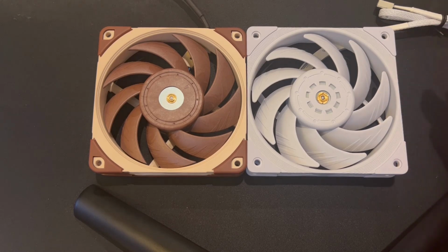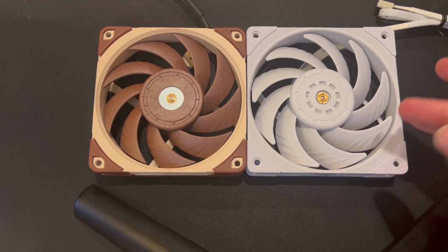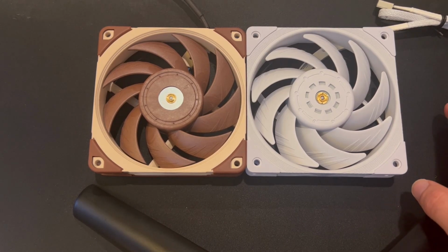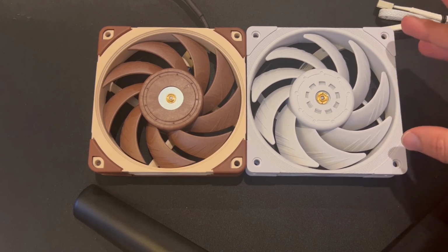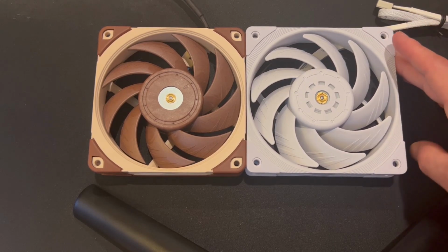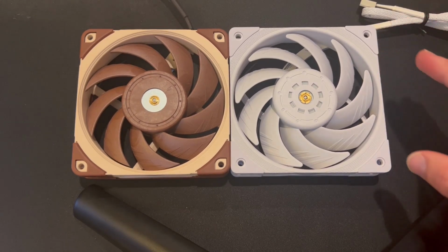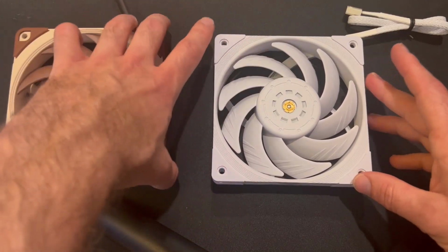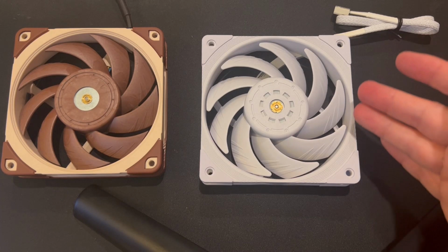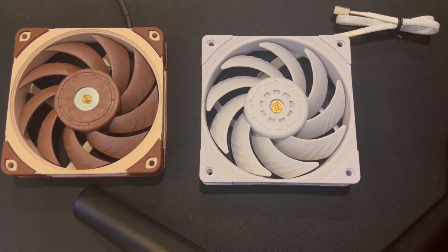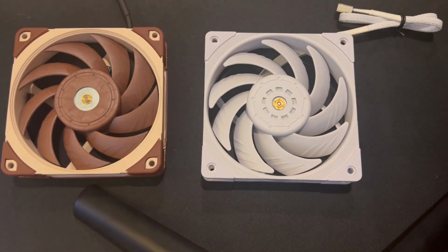On a heatsink, it matters a little bit less because you tend to have just one fan on it and they're a little bit less pressure sensitive. But on radiators, it tends to be more important, especially as you have more than one fan on most radiators these days. But having a good square frame is important if you also have a single fan radiator in a lot of pre-built systems. So overall, the frame design on this lends itself to being good in pressure applications, as well as for sealing and not allowing air gaps to reduce its performance. Well, now I think I've said everything about this fan. Let's move on to my value proposition.